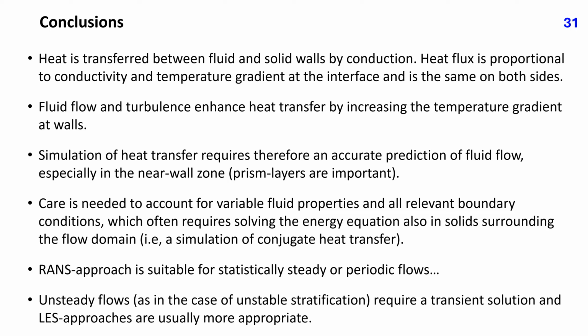Fluid flow and turbulence enhance heat transfer by increasing the temperature gradient at walls. Simulation of heat transfer requires therefore an accurate prediction of fluid flow, especially in the near wall zone. Prism layers are important. Care is needed to account for variable fluid properties and all relevant boundary conditions, which often requires solving the energy equation also in solids surrounding the flow domain, that is, a simulation of conjugate heat transfer.